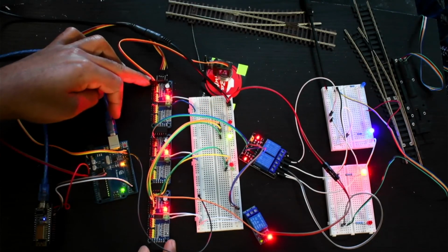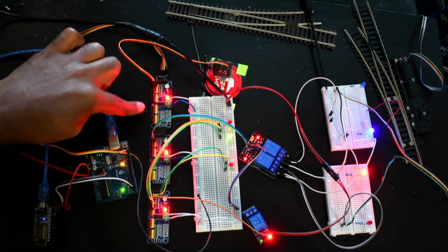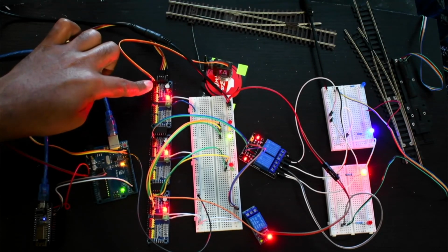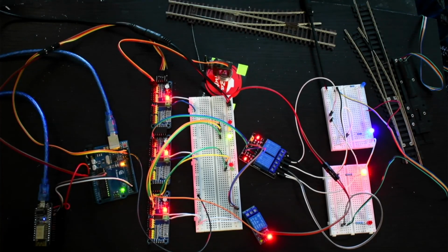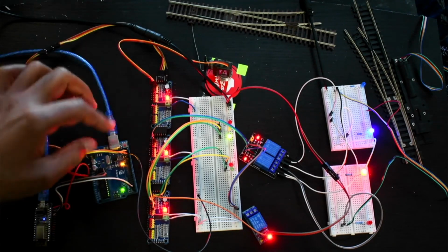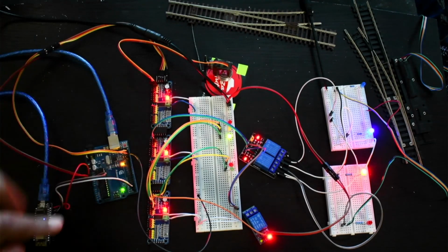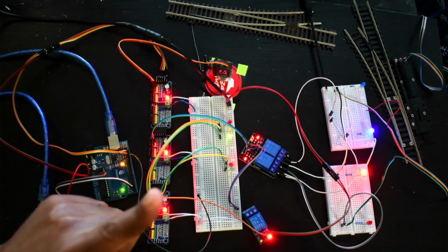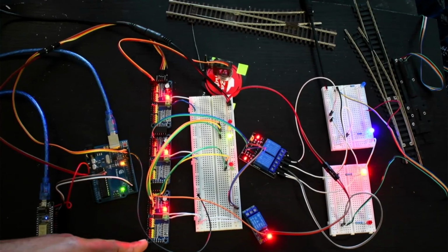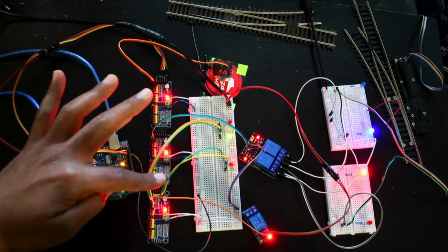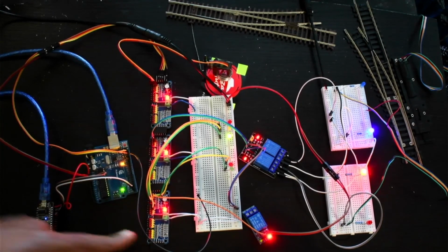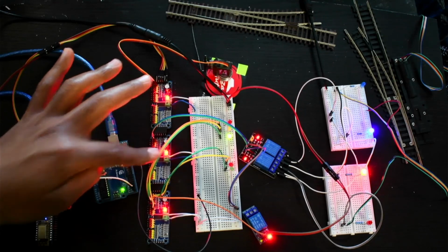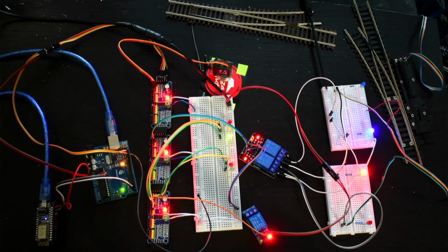So now I have configured only 3 boards. Every board has 16 pins. For servo only 1 pin is required, so every board you can configure 16 servos. For snap turnout you need 2 pins, so every board you can configure only 8 snap turnouts. And for lights only 1 pin is needed, so in one board you can configure 16 lights. For 2 LED signal you need 2 pins, so in one board you can configure 8 2 LED signals. And for 3 LED signal you require 3 pins, so in one board you can configure 5 3 LED signals together.